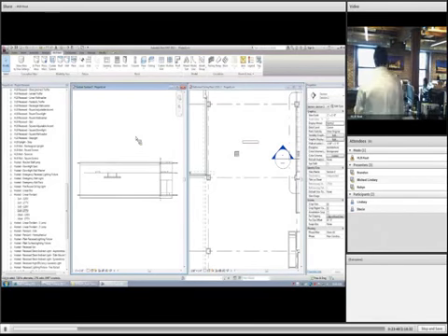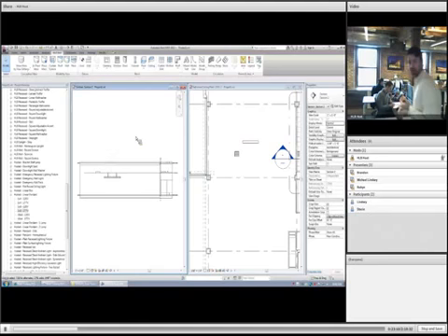So, just to recap, when making the level or a reference plane, something that you can host to, you lock it to a ceiling. That way when the architect's ceiling goes up and down, your fixtures move with it. Placing the fixtures, if you use hosted fixtures, you may need to open up a section at the same time so you can see if they're flipped.